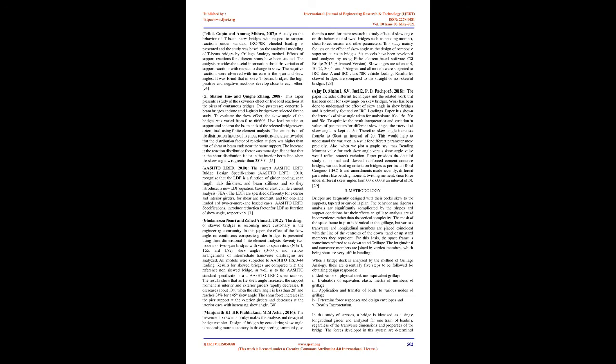2. Literature review. Load distribution factors, LDF, have been used in bridge design for many decades as a relatively simple method to estimate live load effects on bridge members for the design and evaluation of bridges. The load distribution factor concept allows the design engineer to consider the longitudinal and transverse effects of wheel loads as two separate phenomena, thus simplifying the analysis and design of the bridge. The LDF is a function of parameters such as bridge geometry, relative stiffness of components, and nature of the loads.